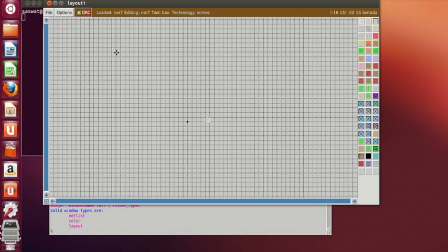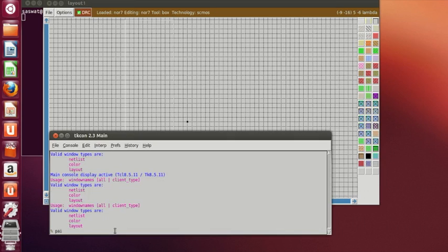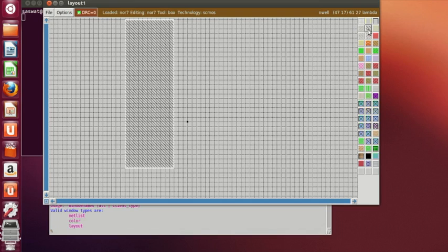So in order to draw the layout from the untwisted form of schematic, first we have to draw the series PMOS. Select the area, then type paint nwell. We will not type paint, we will directly use from here. So nwell, this is P-well, this is nwell. So middle click on the mouse in order to select.